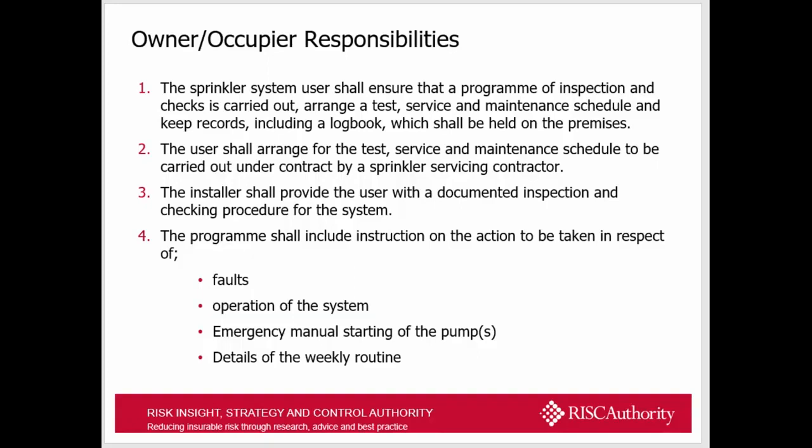service maintenance schedule to be carried out with a sprinkler contractor, and this schedule should be fully compliant to the technical bulletin. Any deviations from this service and maintenance from the provider should be clearly highlighted to say whether it's compliant or non-compliant with regards to TB 203, and the requirements within this particular standard.